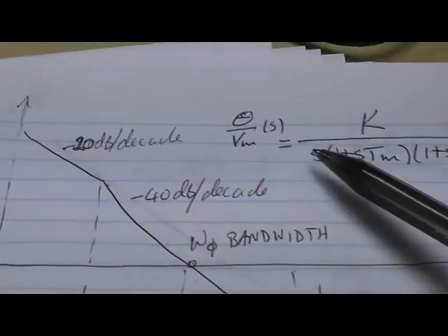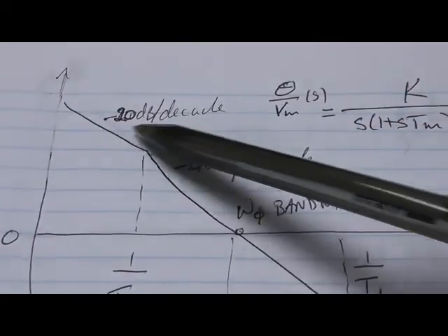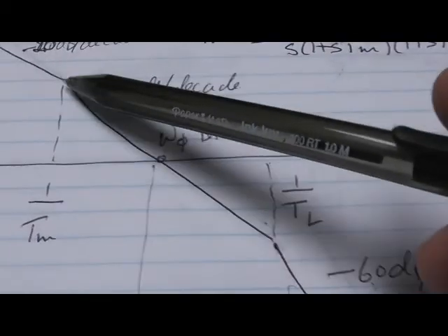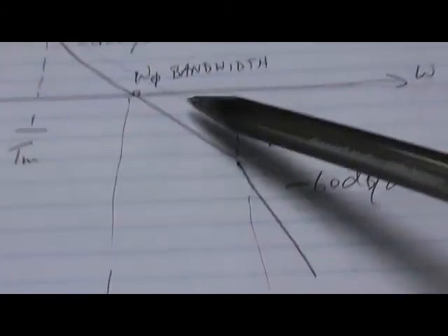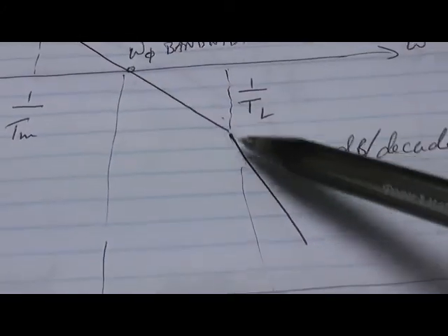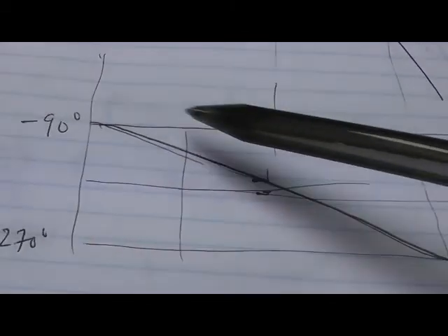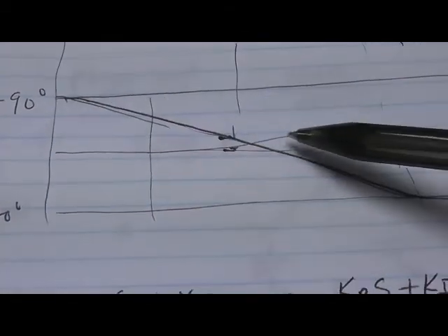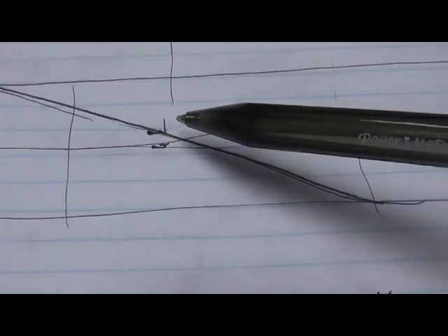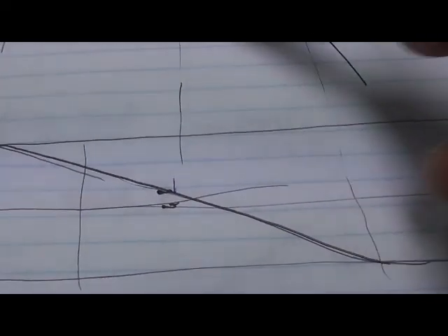Mechanical integrator I explained. So it's got a slope of minus 20 dB per decade, minus 40, passing through unity gain somewhere here. And then finally minus 60. And so that would give us a phase shift starting at minus 90 going down to minus 270, and not much phase margin if we had any. It depends on where we're operating here.